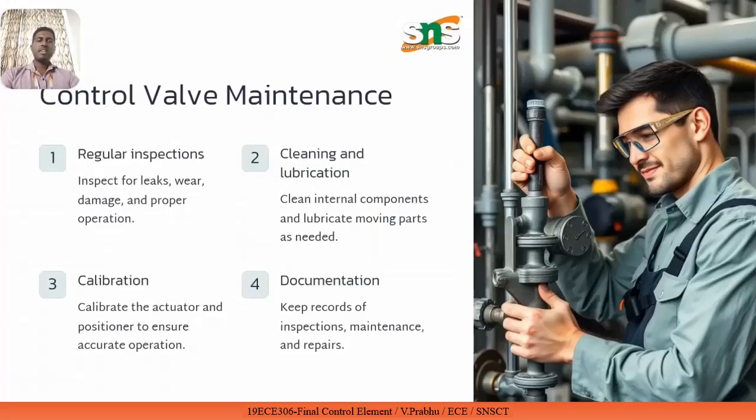And finally, keep records of inspection, maintenance and repairs. You have to enter all these maintenance activities in the logbook so that we can understand what previous steps we have taken on the control valve. So this is with respect to the periodic maintenance of control valves.